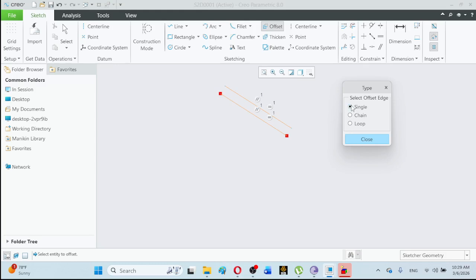Once again, for example, I can click on this type here. I want to offset in the positive direction, meaning in the direction of this arrow. So I can type, for example, 3 units. I am accepting this value like this. So the important point to be noted, when we have applied the single type of offset on the line segment, is what type of constraints are actually defined.